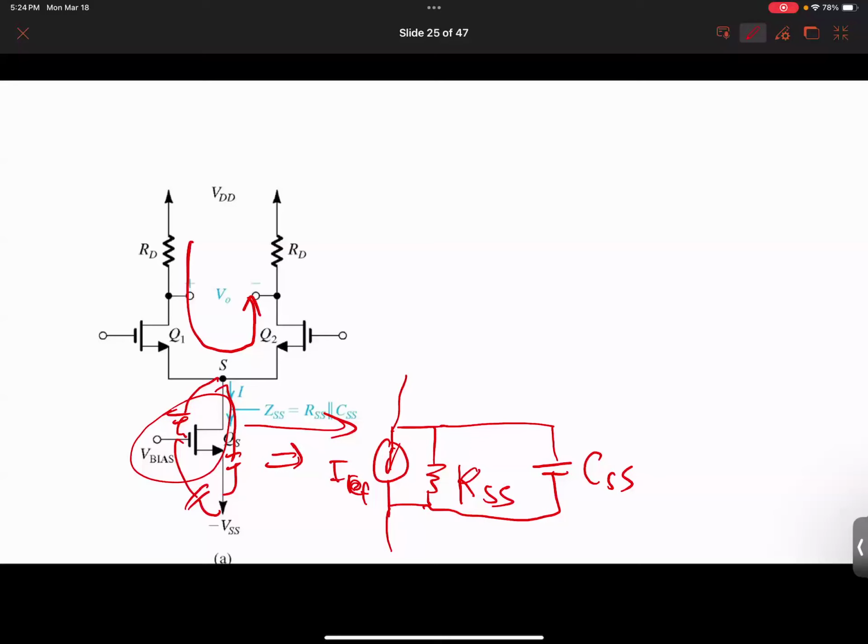It's all gone for differential amplification. So regardless of what I draw here, it does not impact my high frequency response. That's for differential input. So for this one, only this one, right? So that's one conclusion: for differential input, the current source that has intrinsic impedance and resistance does not impact my differential gain.